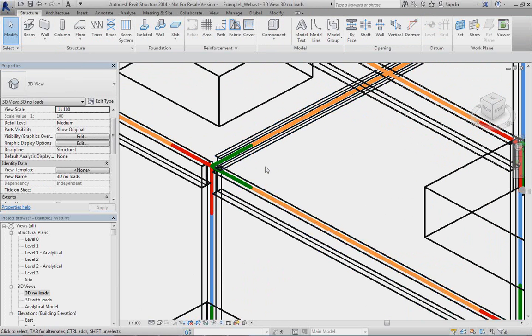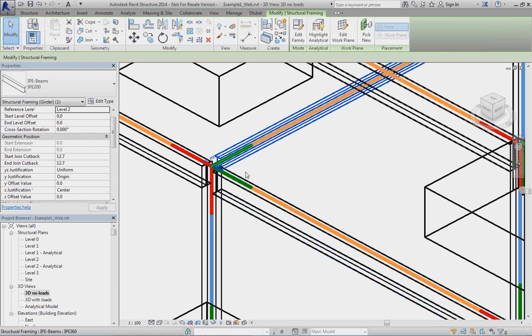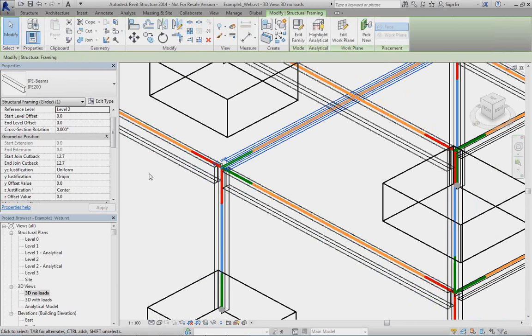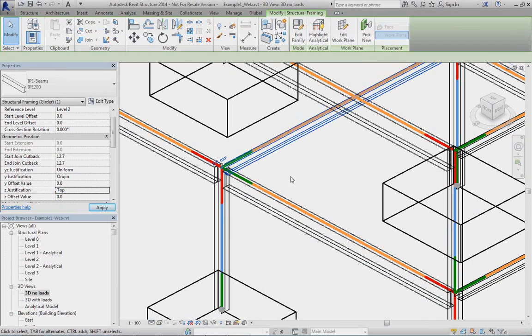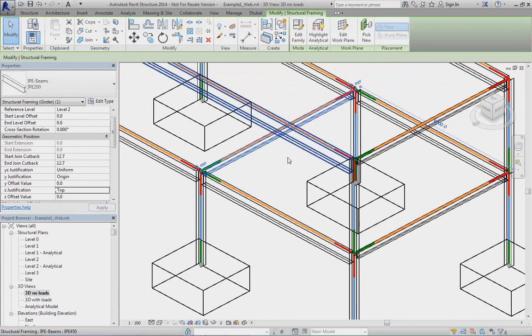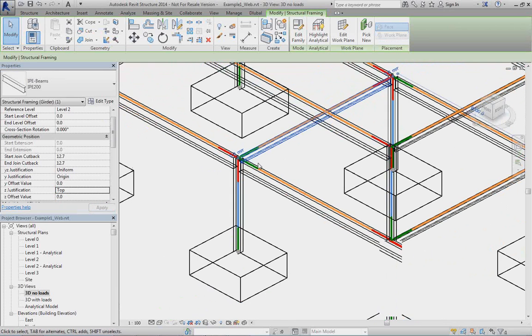If there is a new beam imported from RFEM to Revit, it will also always have center alignment because we don't know how we really want to have it in the real world. In Revit, the user can then adjust it. We'll see this also live later. For me, it was important to point out the two different models and show quickly how you can emphasize them, how you can change them.